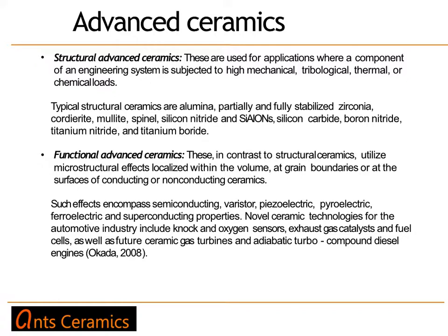Functional advanced ceramics, in contrast to the structural ceramics, utilize microstructural effects localized within the volume, at grain boundaries or at the surfaces of conducting and non-conducting ceramics. These applications are like semiconducting applications, varistors, piezoelectric, pyroelectric, ferroelectric, and superconducting applications.